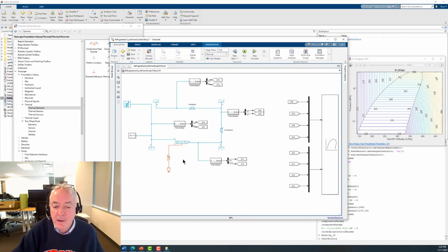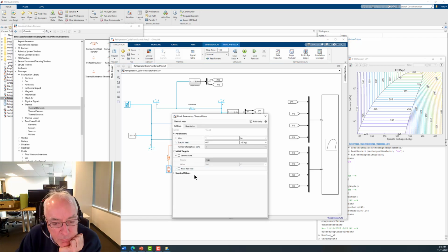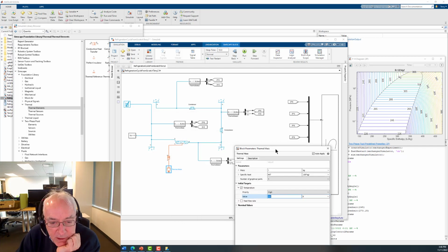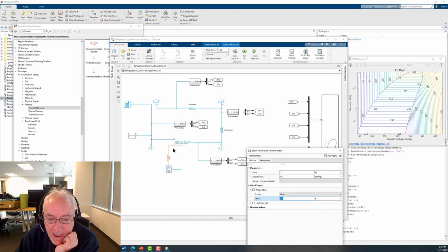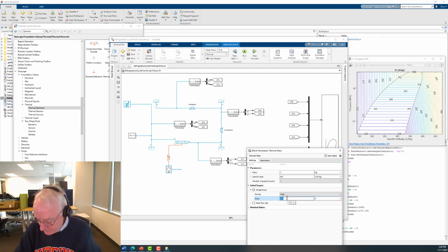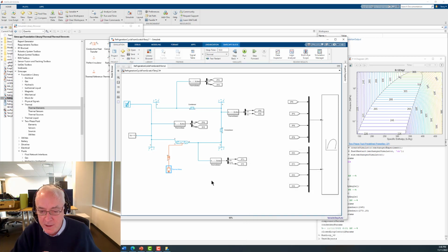And so anyways, to keep things simple, we're going to do what I call a solid to two-phase flow heat transfer rule, right? And I think for this example, let's make sure I get this right, we're going to be adding heat into the pipe. The pipe is operating somewhere, let's say around 270 Kelvin. And so let's make it considerably warmer than that. So we'll put it in at 340 Kelvin. And that seems pretty reasonable. Let's hit run.